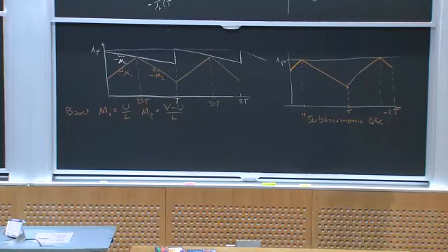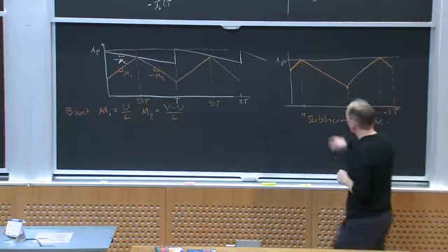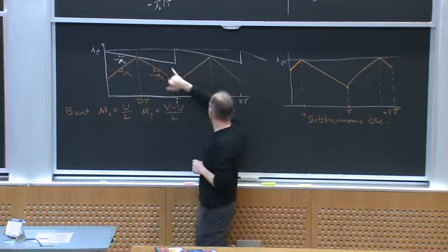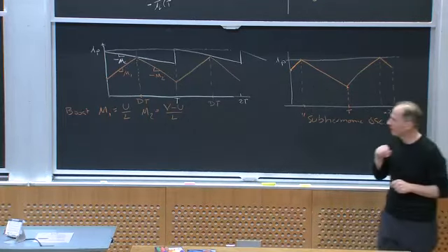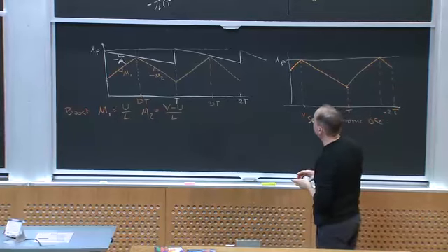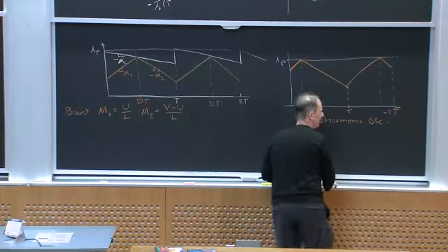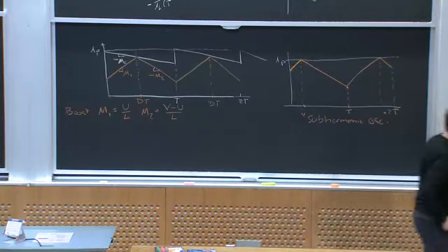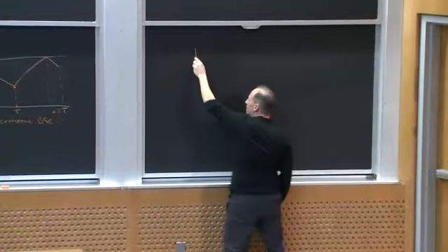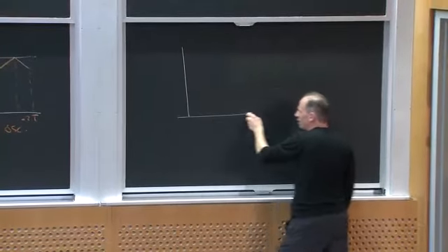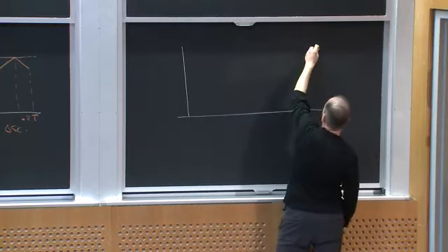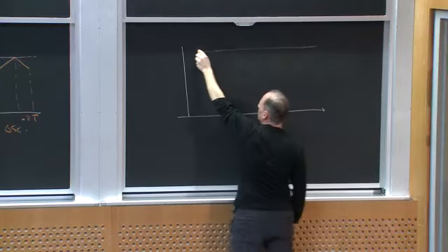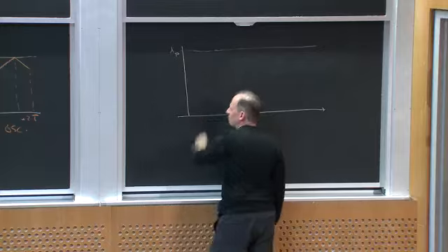But the question is, how big do I have to make this m_c to get this behavior instead of this behavior? And let's analyze that. Let me first start and say, okay, what would my periodic steady state behavior be? Here is I_peak. Here is my compensating ramp.